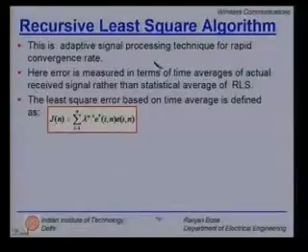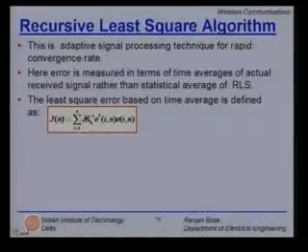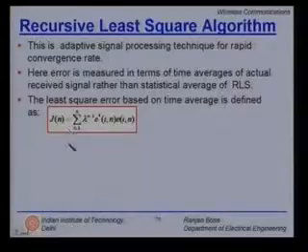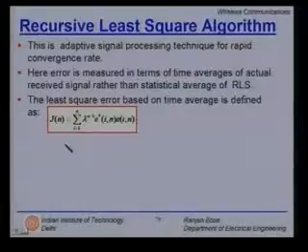See, in the LMS algorithm, if the eigenvalues of the input covariance matrix vary too much, that is, lambda max over lambda min is much greater than 1, it will take a long time to converge. So, we have to put that thing into effect, which is done by the RLS algorithm.